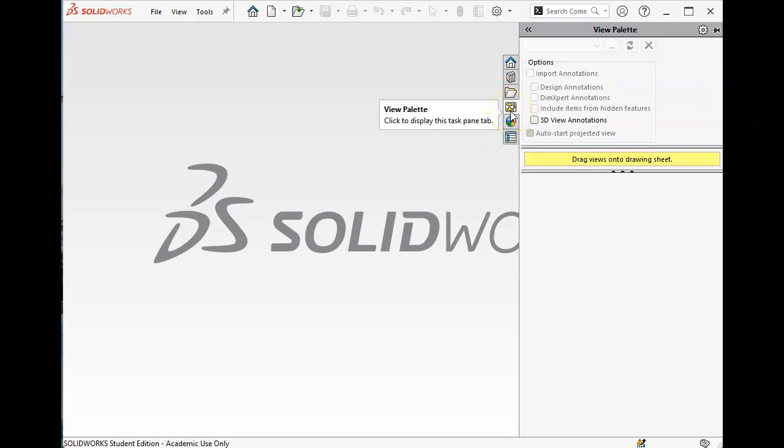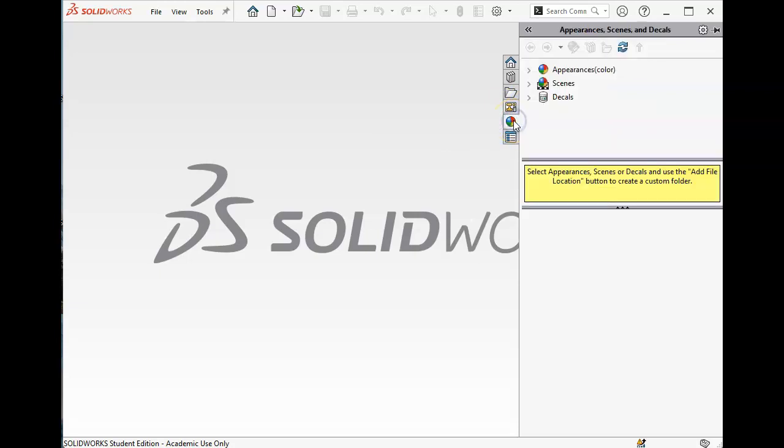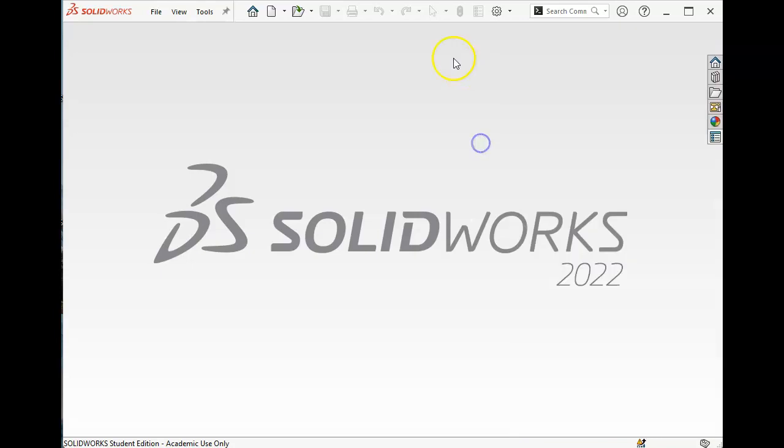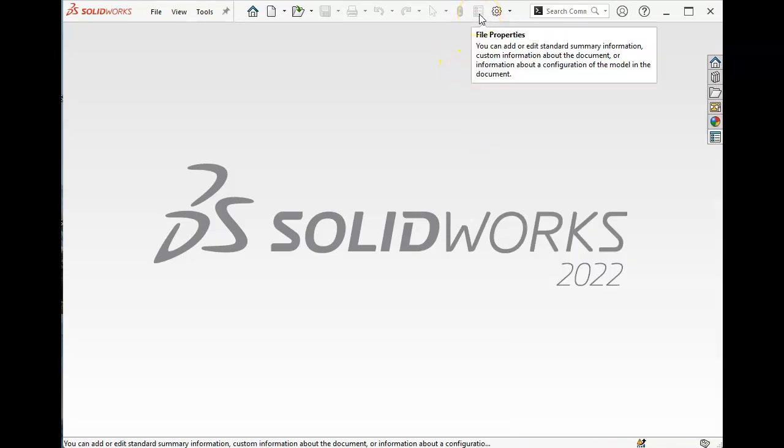The view palette is only available in drawings, so that's going to be grayed out until we can use its functionality. The appearances, scenes, and decals we can tinker with in the parts and assemblies and manage colors of the components, textures, those types of things. And then the property tab builder is controlling metadata, which is the same as if we have a file open, going to the file properties, just a little bit easier interface.